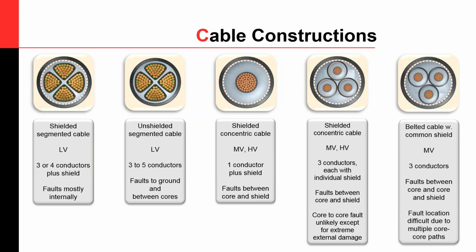The field is not symmetrical, so the stress is not distributed symmetrically. And here you can have various different scenarios also for the fault, which can be a phase-to-phase fault. But as I said, this is predominantly for the laminated cables, for the PILC cables, and so this doesn't really apply for extruded cables.